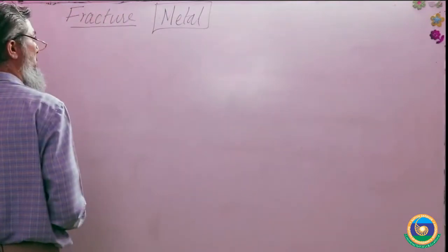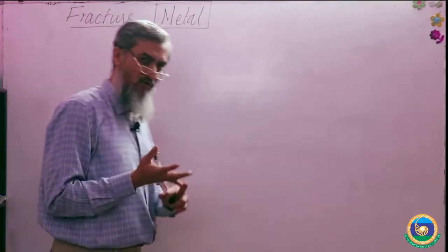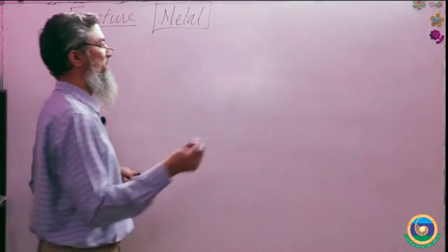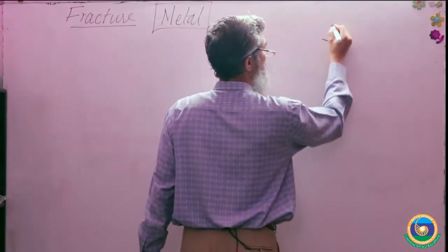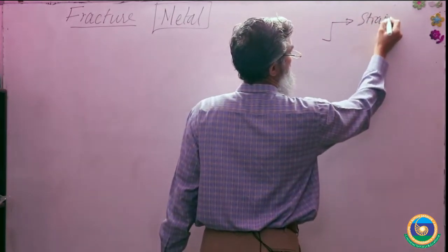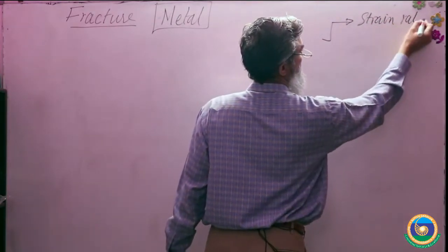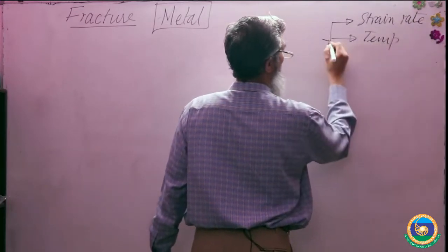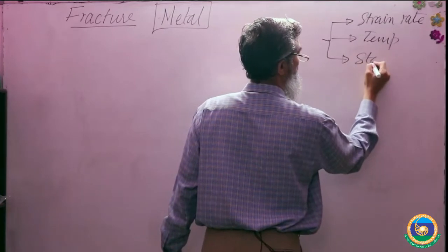So metals will also fracture either in ductile mode or in brittle mode, depending upon three things: strain rate, temperature and state of stress.